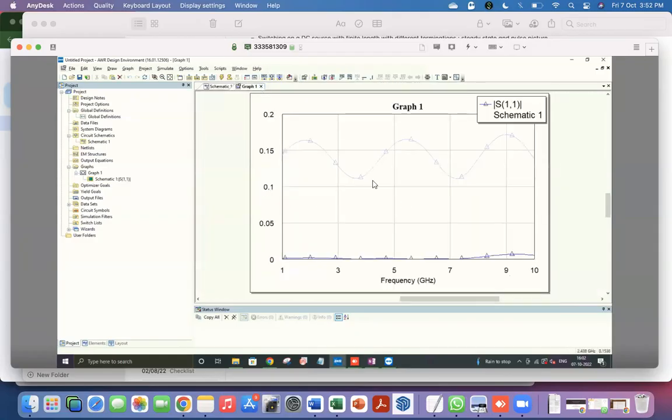So the reason I actually spend a little bit of time on this is that this is one way you can, by understanding how the reflection coefficient would change, if you're dealing with an unknown transmission line which you have designed, you can actually guess, are you above or below 50 ohms, and sort of know what to do to get to the right value. Because here, of course, I could just change the numbers continuously till it matched. In a real thing, you cannot make infinite number of transmission lines with varying width to get it correctly. Okay.